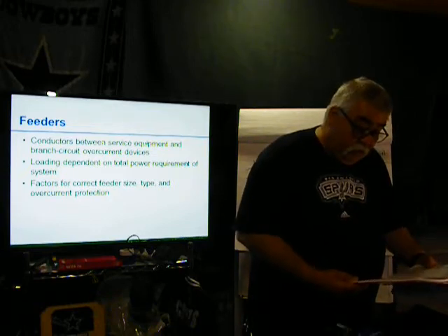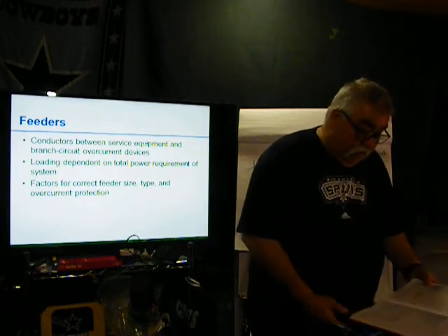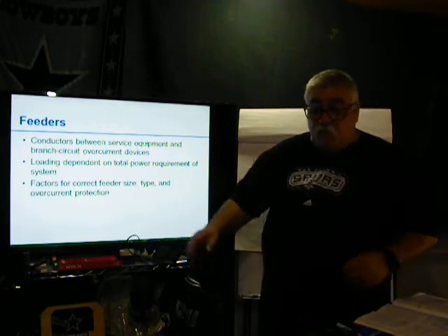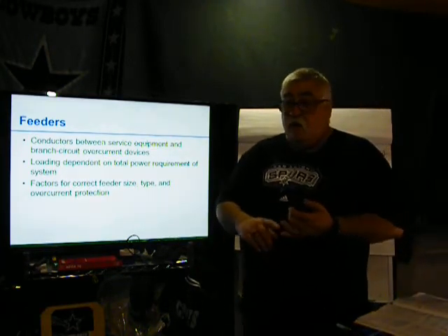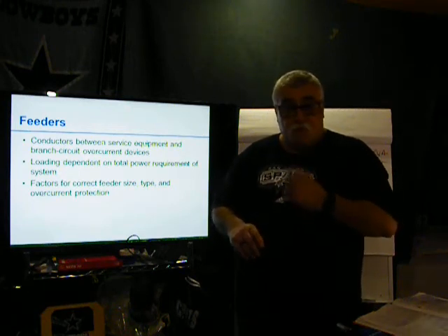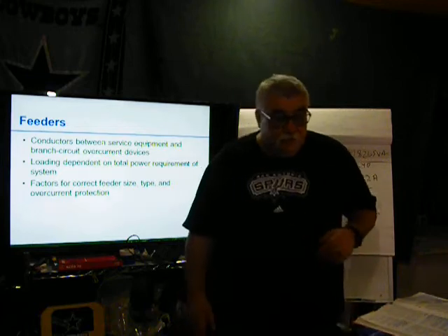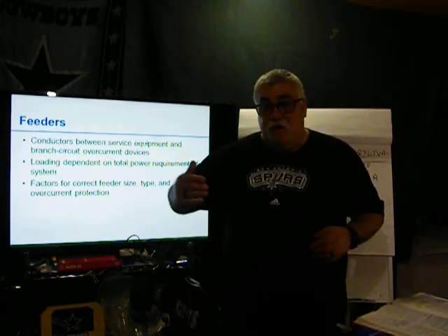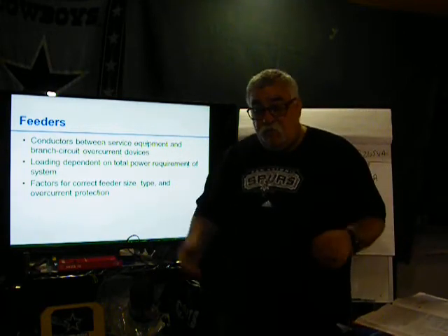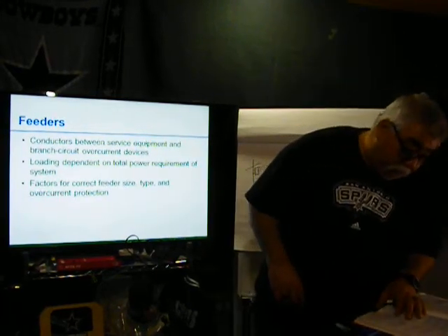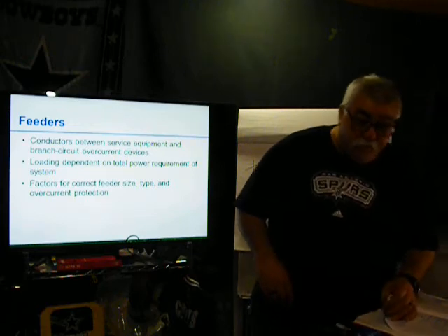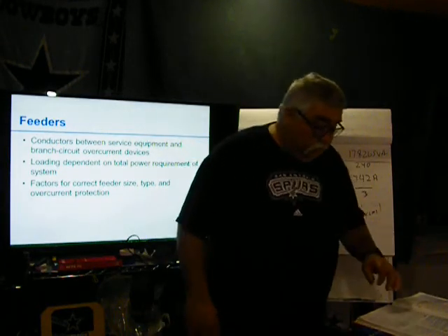Demand factors. Continuous loads may affect feeder. So demand factor, what's a demand factor? That's a table where if you have a dwelling, a hospital, a hotel, motel, and a warehouse, you can derate. So it's a demand factor. You can change the demand factors on those areas. Okay, we got a bank or a store, we do it at 100%. Protection. Various overcurrent protective devices can be used with feeders. You can use breakers, fuses.